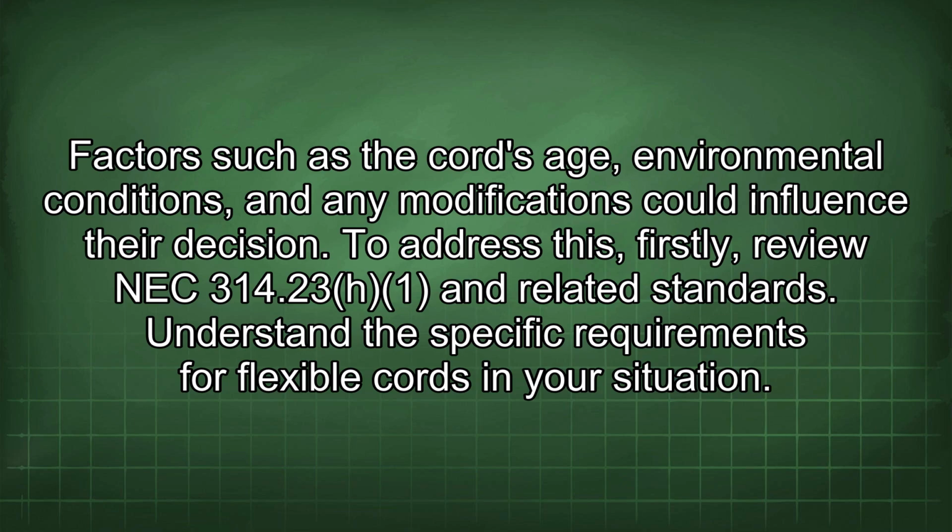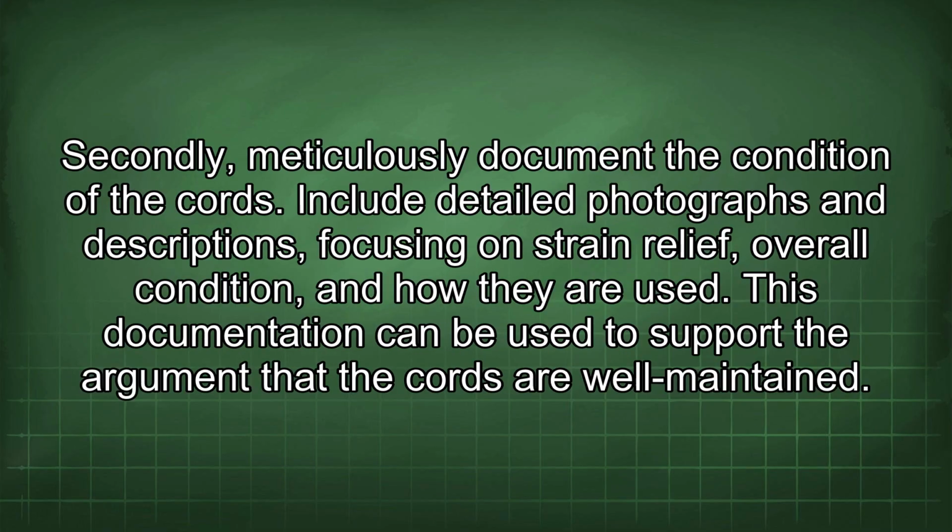To address this, firstly, review NEC 314.23 and related standards. Understand the specific requirements for flexible cords in your situation. Secondly, meticulously document the condition of the cords. Include detailed photographs and descriptions focusing on strain relief, overall condition, and how they are used. This documentation can be used to support the argument that the cords are well maintained.